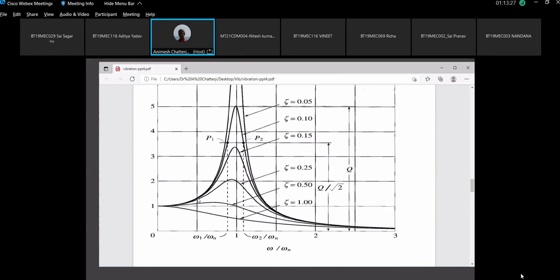So now what will our vibration value be? 1.3. So you have reduced the vibration from 5 to 1.3. It is a tremendous improvement. How did the improvement happen? Simply by changing the isolator pad. That's all. We fitted a new isolator pad. The machine's vibration reduced from 5 to 1.3. Now you can go to your boss and ask for promotion and you will get the promotion. So whatever we are discussing, it has practical usefulness.